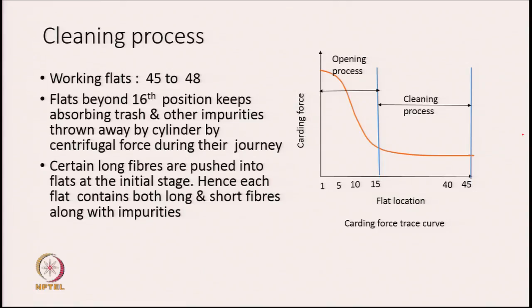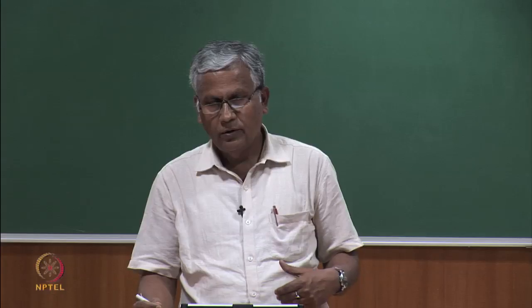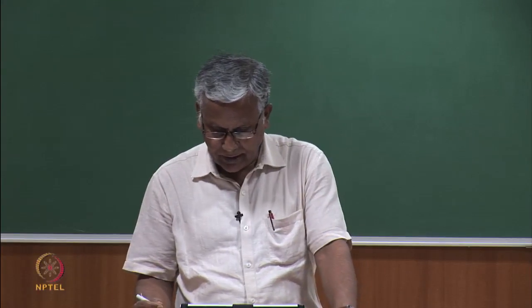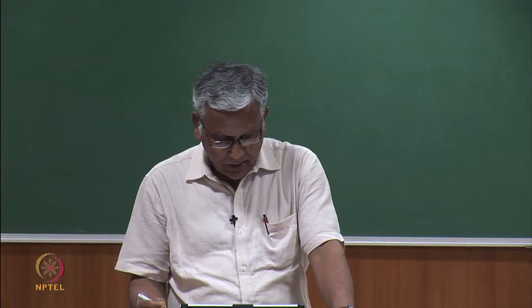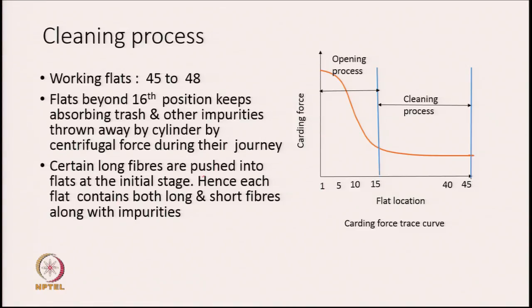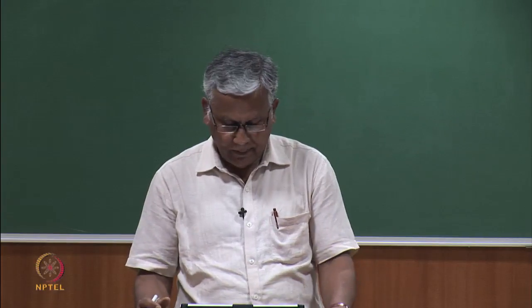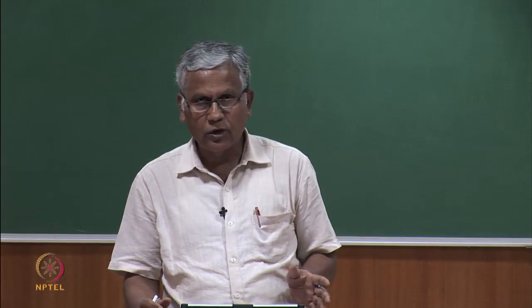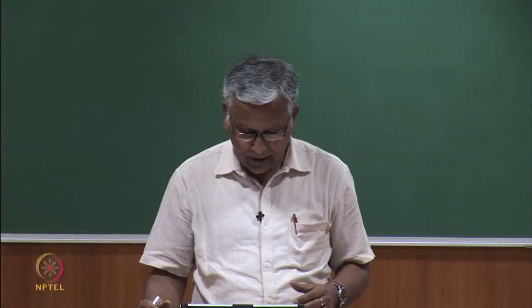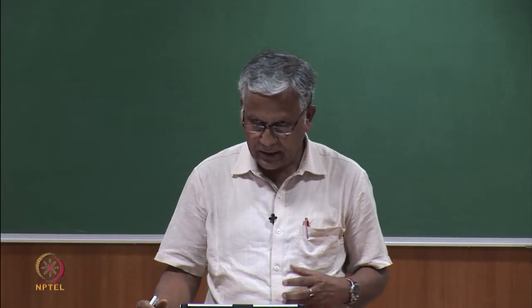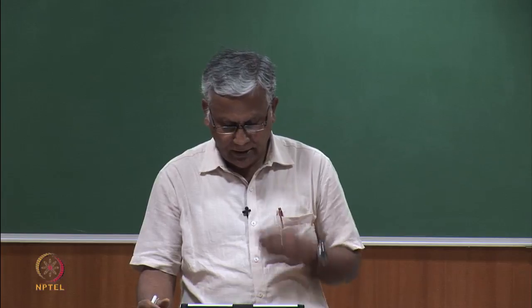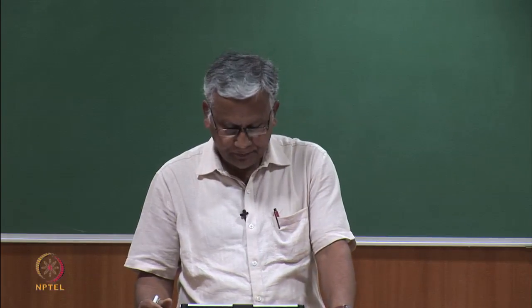Now, what we find in the flat strip is that there are a lot of long fibers in them. These long fibers are actually pushed into the flats at the very initial stage of opening, when the tufts are approaching the carding zone; at that time all long and short fibers, everything, is pushed into the flats. There is no discrimination in selecting the fibers.